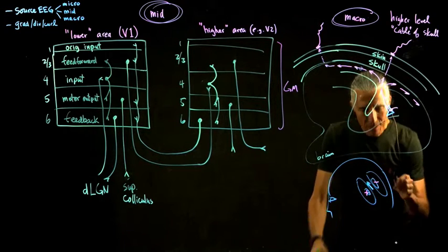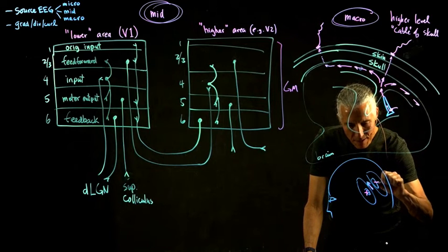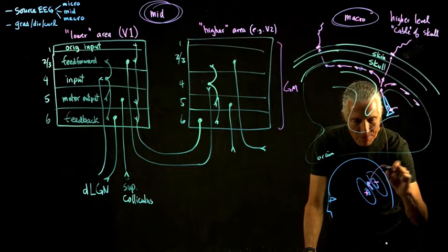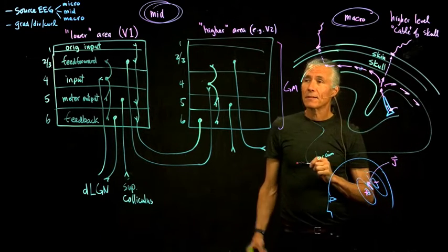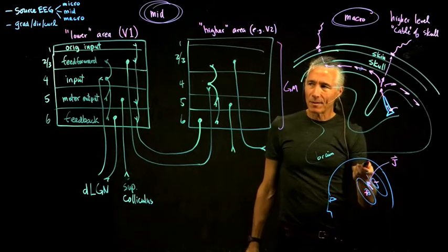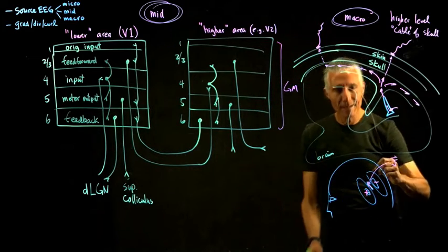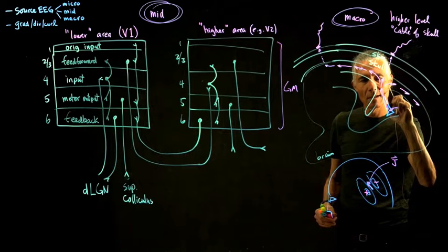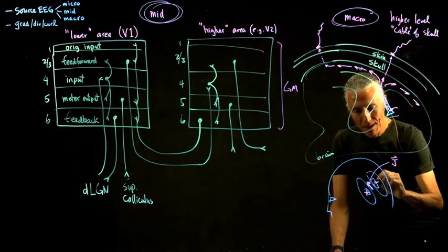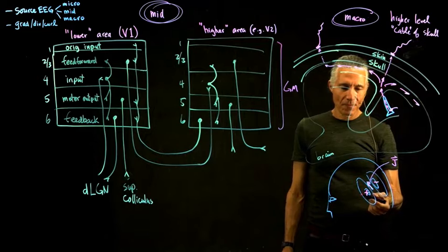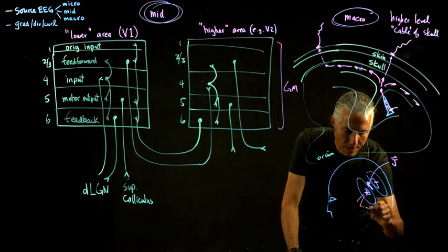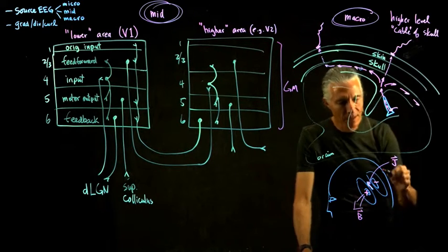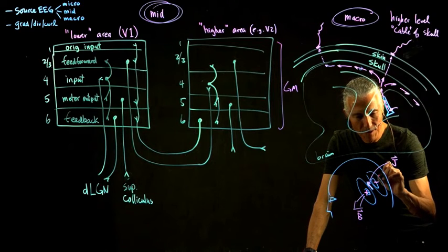So this guy right here is the current. So the current is a vector also. The voltage is just a number, but the current is a vector. So that's a current going in some direction, like for instance this direction. And then that creates a magnetic field vector. So the magnetic field vector is going to be sticking out of the head on this side. So that's the B vector. And it's going to be going into the board.